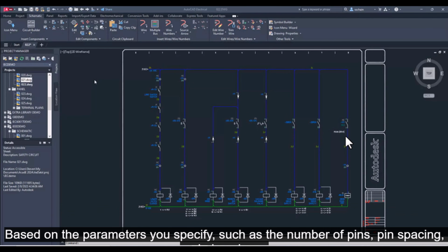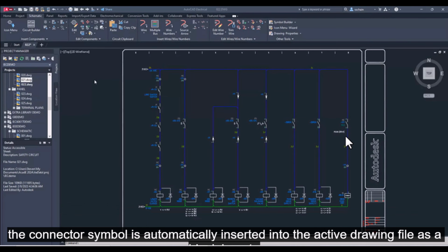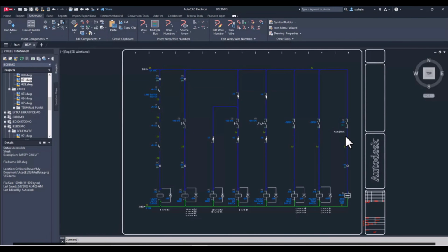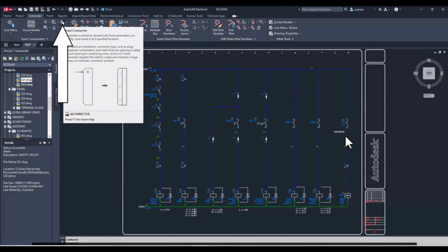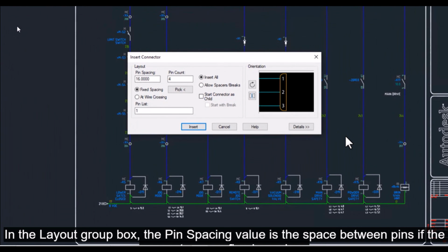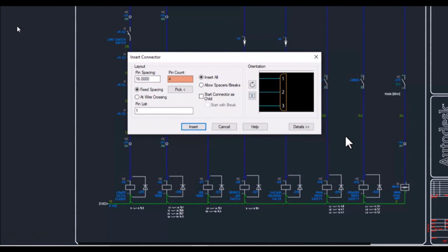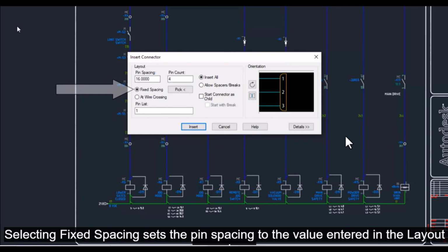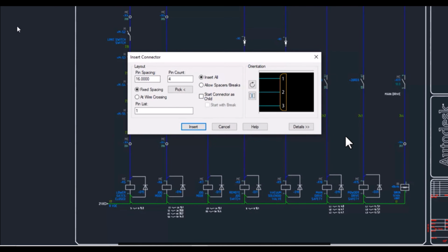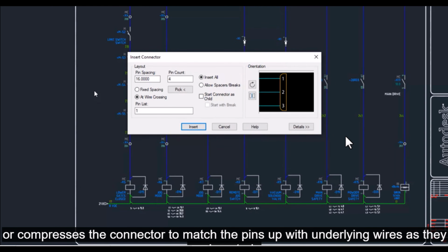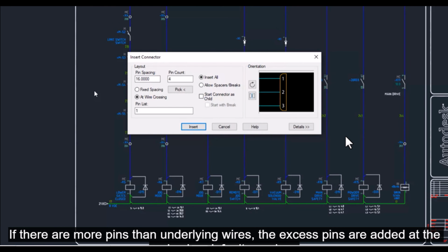What happens then? You might see a wire on the screen, but it doesn't show up in the report. Or maybe a wire number just refuses to update. Running a rebuild forces the software to rescan every entity on the drawing and update the database records to match. It's the first step in troubleshooting any weird error. So have you tried turning it off and on again? Have you tried rebuilding the project database? Pretty much. It solves about 90% of the ghost problems where the visual just doesn't match the data.